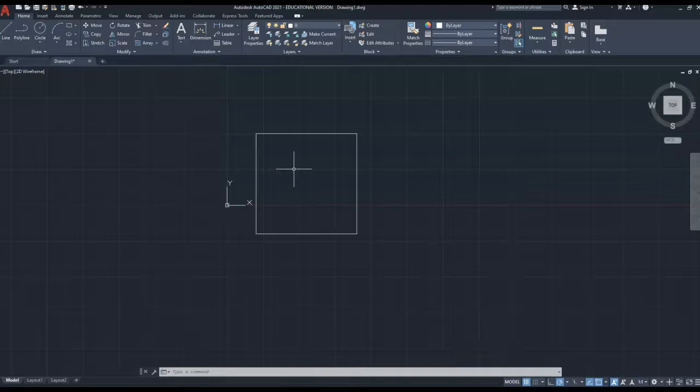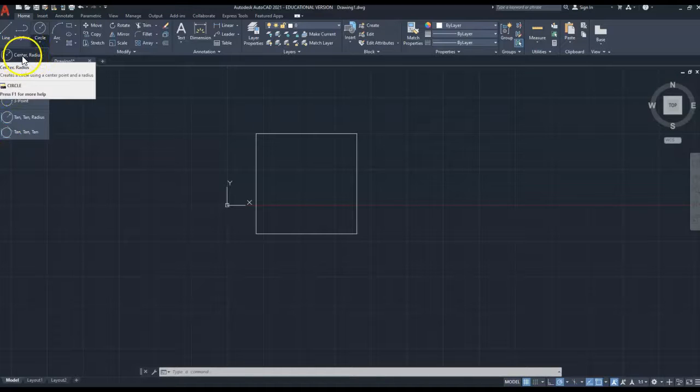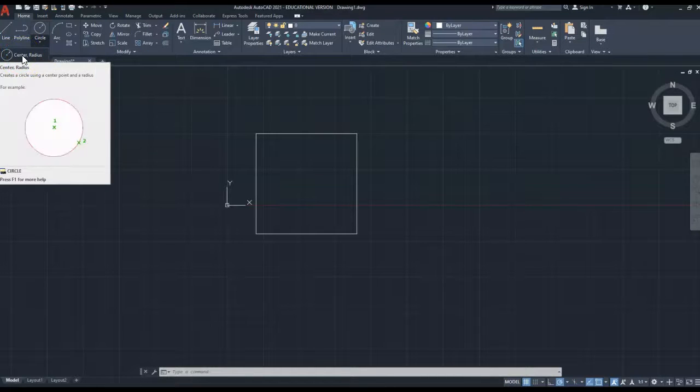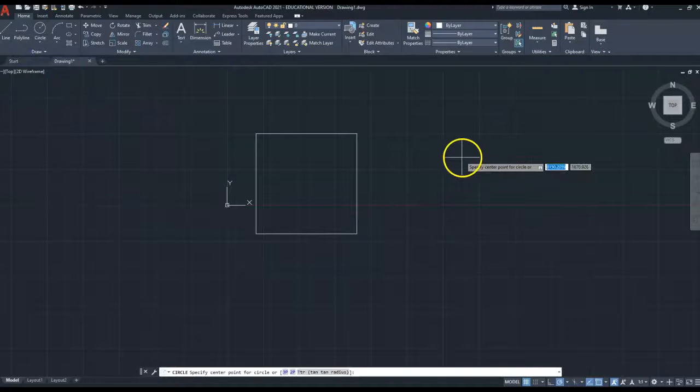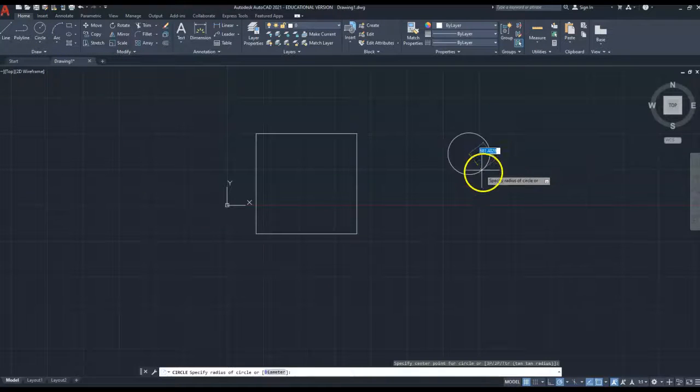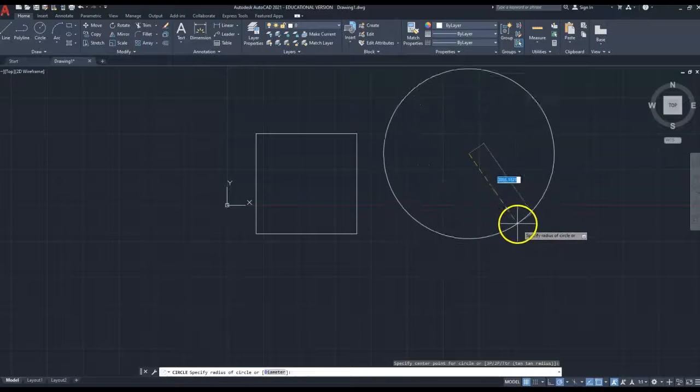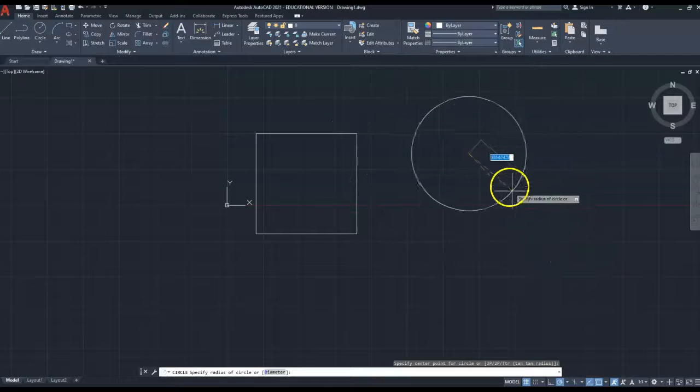So that's basic line drawing. You can do whatever you want, and we'll go into a little bit more detail in a minute. But as you can see up here, there's all sorts of different options. So let's think about doing a circle. If I click circle, I've got other options. I can do 2 point, 3 point, tangent, radius, whatever I want to do. If I want a simple circle, and I know the radius is 4 meters, say, I click that, come down here, left click again, and pull the mouse out, and I can make that as big as I want.